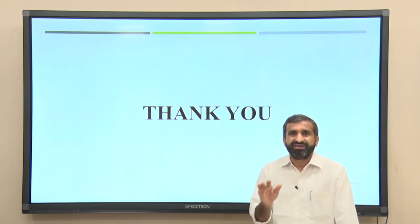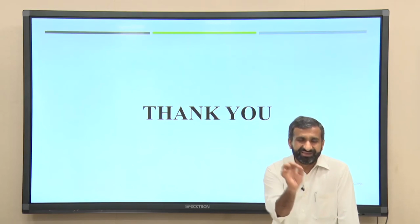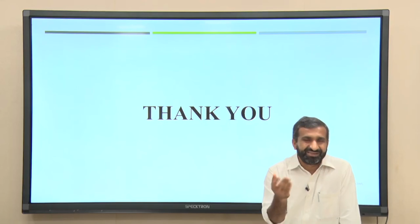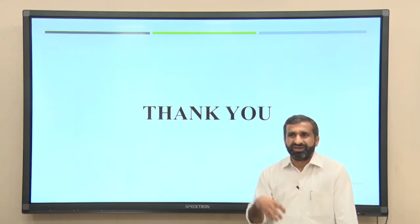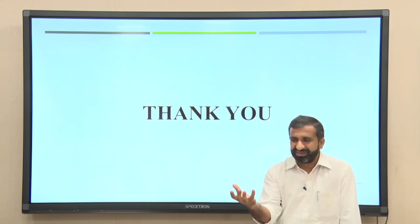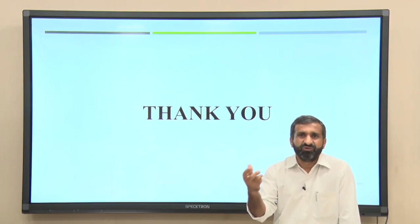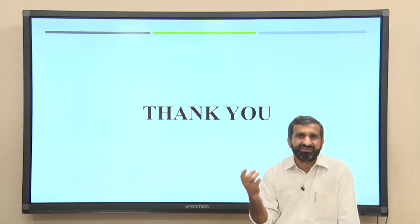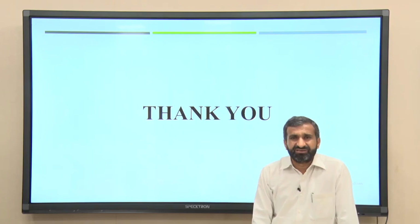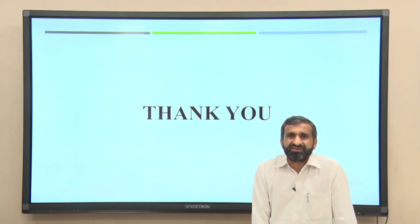Here we will finish, but before finishing, one last comment on landfills. I am repeating that waste which is not biodegradable, not recyclable, not utilizable in any way should only come to the landfill area, so that you need not worry too much about the leachate. Wherever a small landfill facility is created, go for proper lining and a proper leachate collection system. Maybe we will not be able to treat the leachate because it is a very costly system, so at least plan a facility where the entire leachate can be recirculated onto the same area. That is the best way of operating a leachate collection system, followed by treatment.